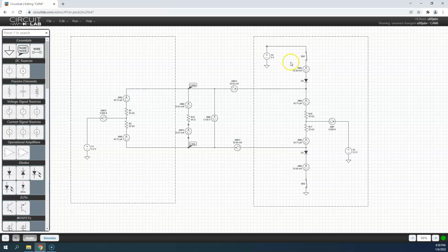We're actually starting to load this bus down. It's more current than we might be able to source with this. So we've got to be careful. That's one of the reasons we don't want too many devices. It's the same thing as putting a bunch of light bulbs on a truck or a tractor. You put a bunch of lights there, everything's going in parallel. Eventually you're going to blow a fuse, right? Because you've put too many lights. People who use LED lights now, it's probably not applicable, but back in the days of incandescent lights, you couldn't put so many lights. Eventually you're going to blow a fuse or pop a circuit breaker, right? Because you just keep increasing the amount of current, each one of these.